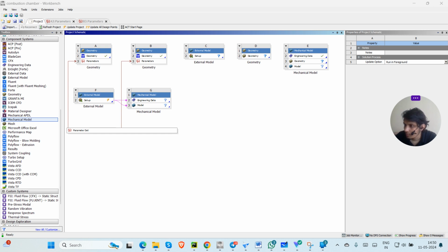So now let me give you some workshop description. The purpose of this workshop is to simulate transonic flow over a two-dimensional NACA 0012 airfoil and compare the result with experimental data. This workshop solves a compressible flow, because obviously above Mach 0.3 to 0.4 the airflow becomes compressible. We will monitor lift and drag, again comparing with experimental data. The learning objectives are to understand how to solve compressible flow and how to compute lift and drag in external aerodynamics applications.